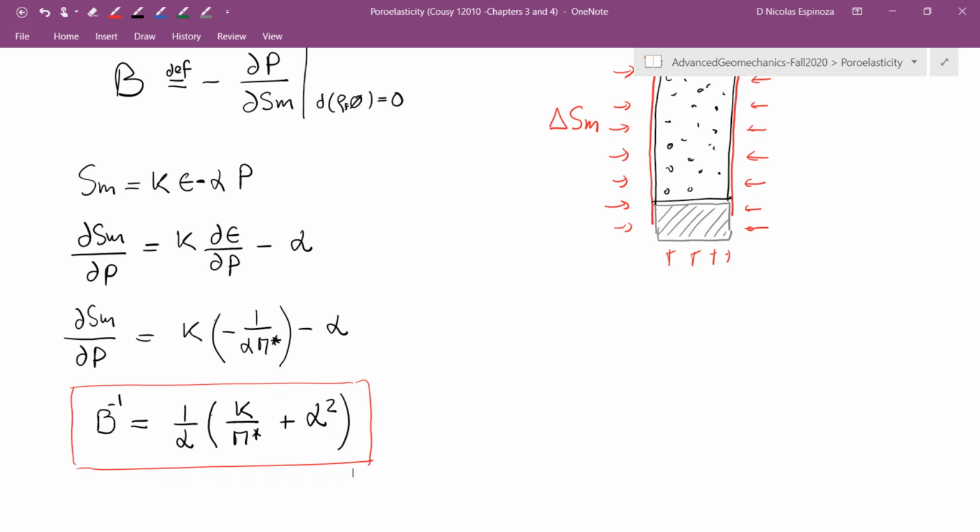So as I mentioned before, this Skempton parameter is important in order to get to know if a sample is fully saturated, and in order to do an undrained loading if needed, and also in order to get to know if the sample is fully saturated, so the P wave that we measure is the one that corresponds to the P wave in fully saturated conditions.